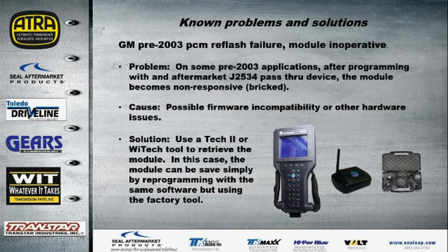So with that in mind, GM modules, they're resilient. A lot of times you can get them out of the junkyard, dust them off, and flash them, and they're just as good as day one. They just want to be loved. So in that case, you want to just try the good old home solution of the OEM tool to wake that back up.